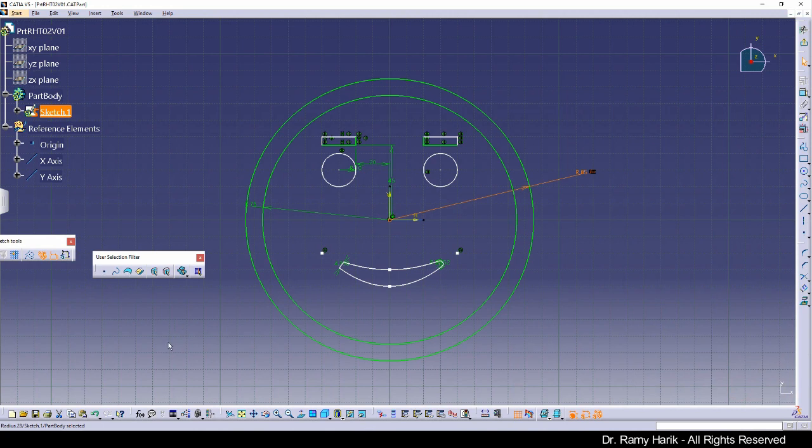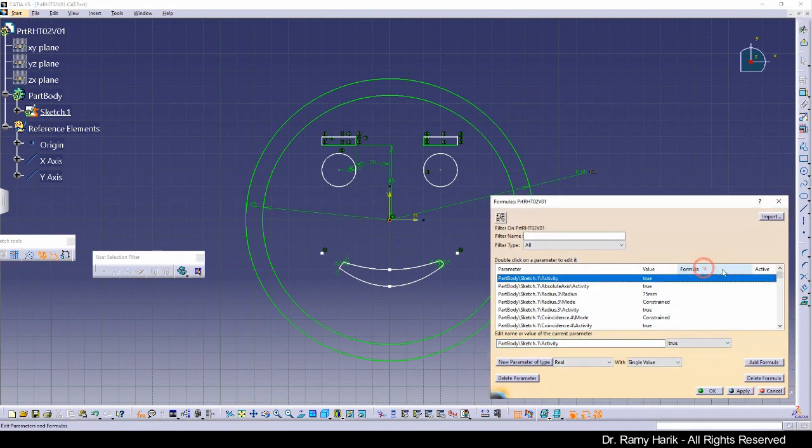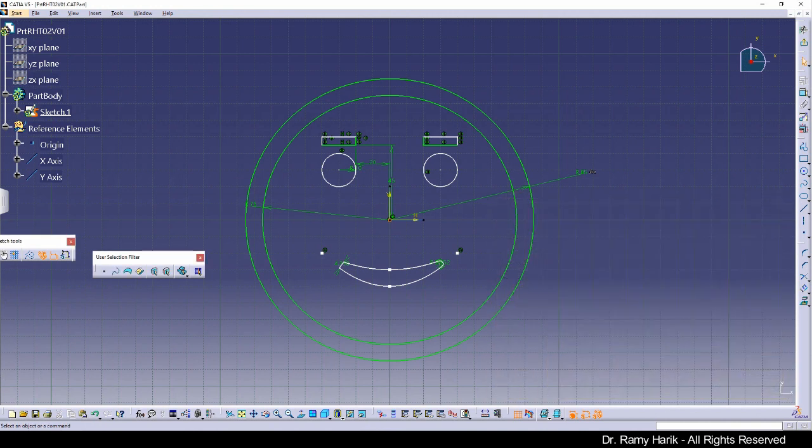All right, in case you want to see all the formulas you have created, you can select this formula element in here and it shows you, like, radius 28. So this is for our circle, which has a value of 85, but it's coming from the formula that we have created. Further down the road, we will demonstrate a little bit more the capacity of formulas and using Excel and so on. So now that we have the formula, we're going to trim the circle.